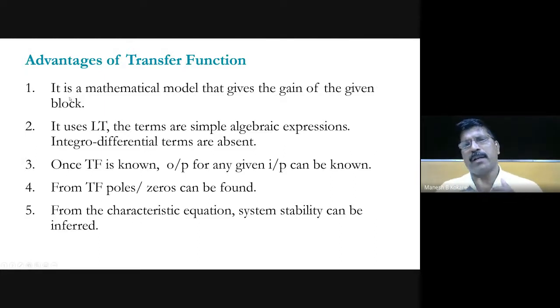Number one is that the transfer function gives the mathematical model, and that is nothing but the gain of a given block. Second thing is that for finding the transfer function, we use the Laplace transform. This Laplace transform will convert a higher order integral differential equation into a simple algebraic equation, so solving those equations is easy. Okay, so that is the second advantage. Third advantage of the transfer function is that once you know the transfer function, you can determine the output for any given input. Okay, so that is the third advantage.